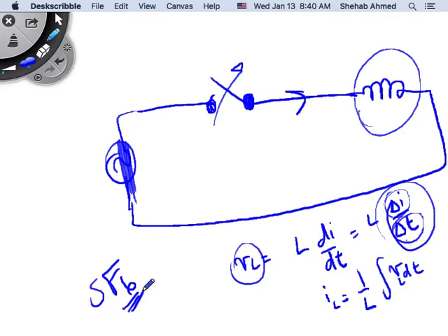a big room, and they will have the corresponding switchgear inside them as well. So the measurement devices will be inside, as well as the circuit breakers and the bus bars. So the bus bars will be immersed in the gas. The current and voltage measurement devices will be immersed in the gas, and the circuit breakers will be immersed in the gas. It's like big cylinders, and you will not really know what it is from outside until you go and see. Okay, it will say GIS on it, or gas insulated switchgear on it.